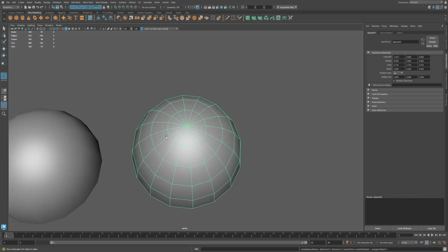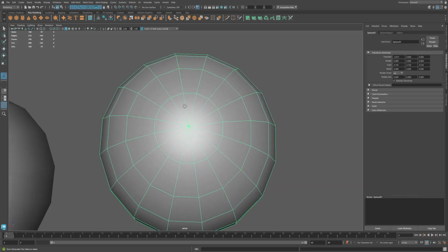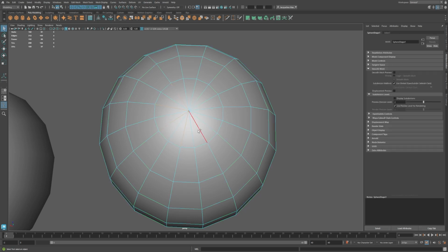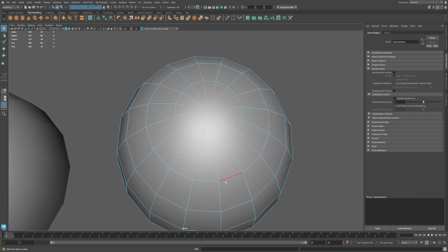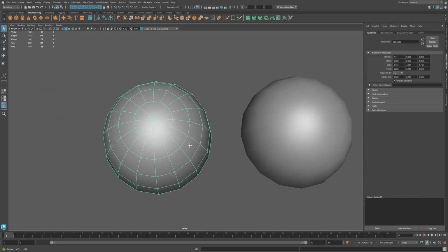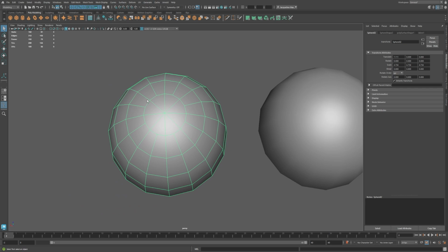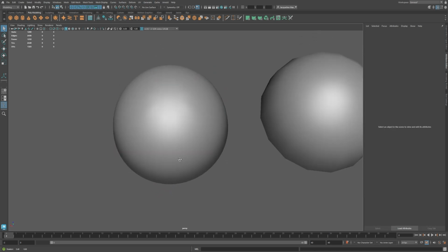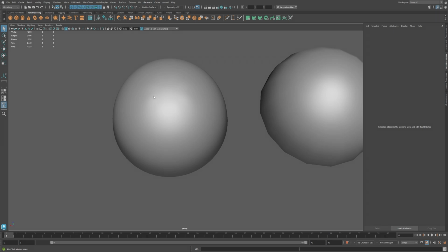Now, what's often asked is, if we're trying to do quads, why not just delete every other edge so that this then becomes a collection of quads instead of a collection of triangles? That's what's illustrated over here. Now this is technically not made up of any triangles. This is all four-sided faces. But now when I smooth this, it's more subtle, but you can see the same effect.